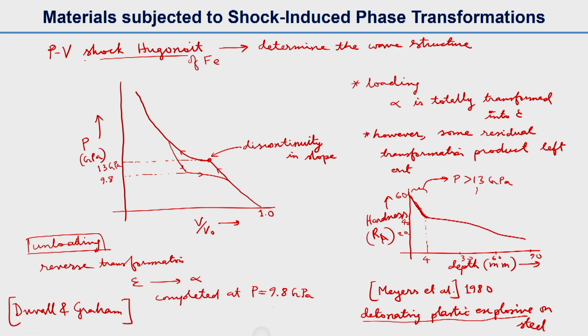That's why transformation happens, that region is transformed, and that's why hardness is very high, and the other region, this side of that region, is untransformed. So you can see that hardness can go up to very high, this is RA number 60, because of this transformation.